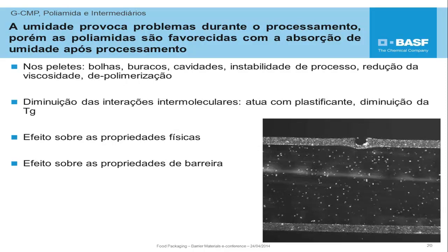According to what we know, humidity is very harmful, since a plastic material that contains more or less important amounts of humidity will, in general, have various more or less important problems in extrusion, like a fall in the viscosity of the material, and possible reversal of polymerization, depending on the case.